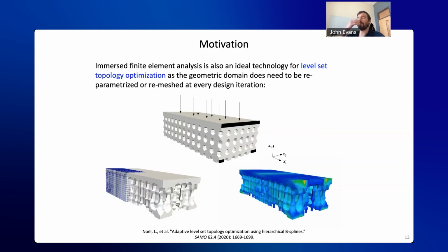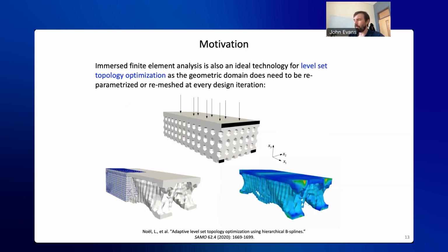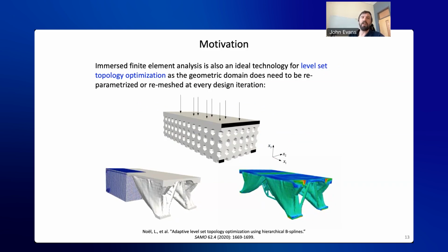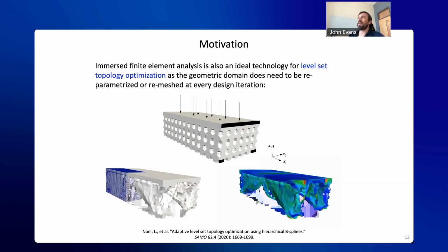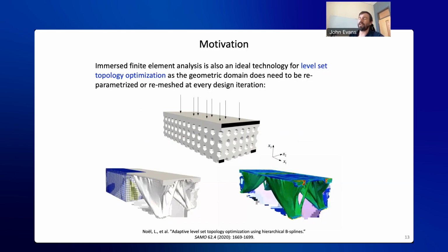And what motivated us for this particular project was level set topology optimization. Immersed finite element analysis is ideal for this application, as the geometric domain does not need to be parameterized or remeshed at every design iteration, with the caveat that you may need a mesh for integration, right?